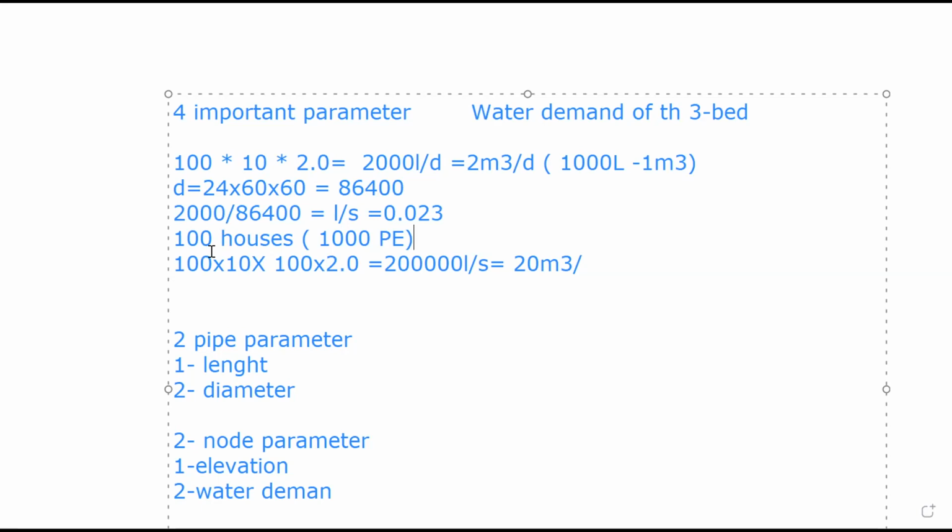So I will simply eliminate this 10 again and just leave it at this. This 10 is my population, the number of persons I'm designing for. I know they are fragmented into 100 houses, sorry. Then this 100 is the water demand per person. And this 2 is the factor of safety, the peak factor. There are 2 peak factors that occur in a day, morning and evening. I think we discussed all those things yesterday when we talked about the demand pattern.